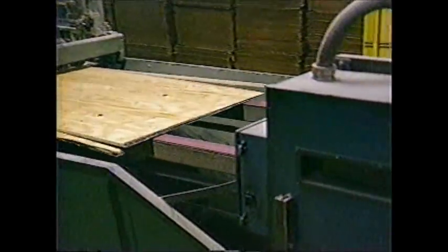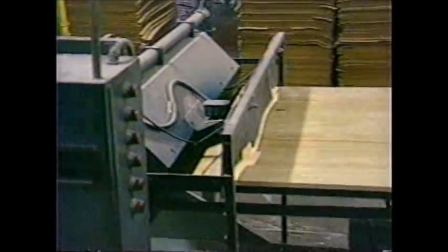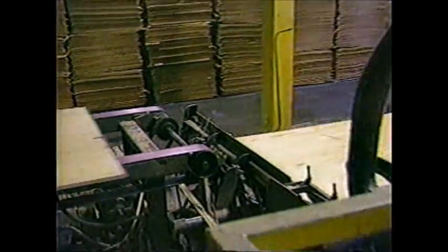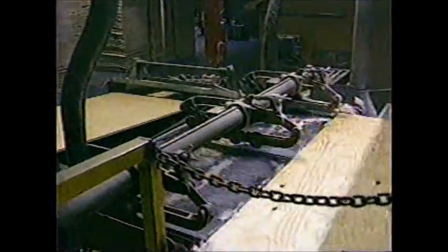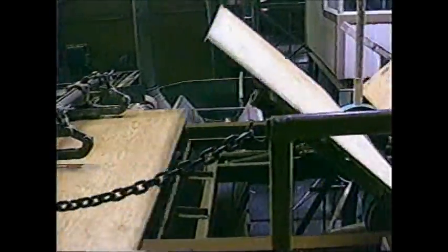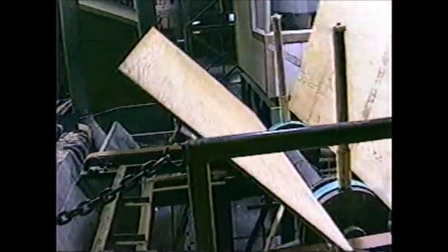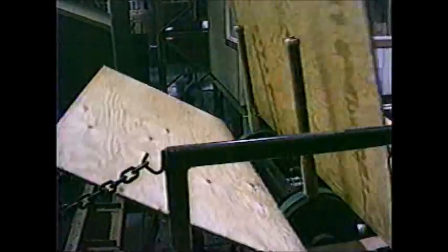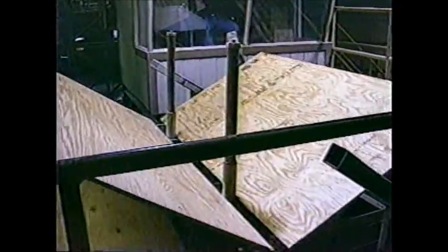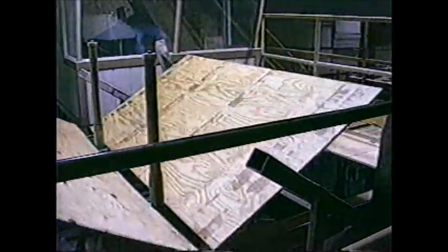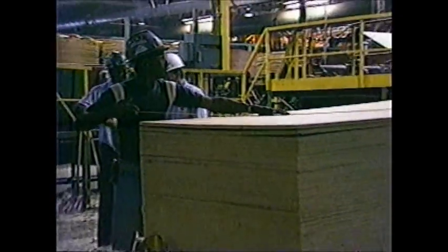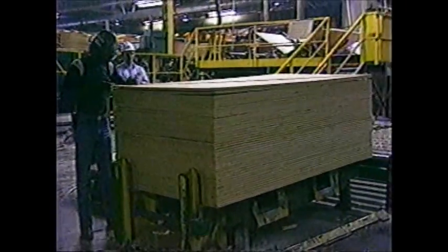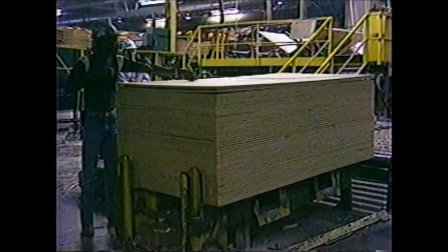After cooling, the panels are trimmed to a standard size, such as 4 by 8 feet. The trimmings are pulverized and used as boiler fuel. The panels then pass a grading station where each panel is graded front and back and routed to the proper bin by the grader. The panel dimensions are constantly spot checked to ensure they are within APA limits.